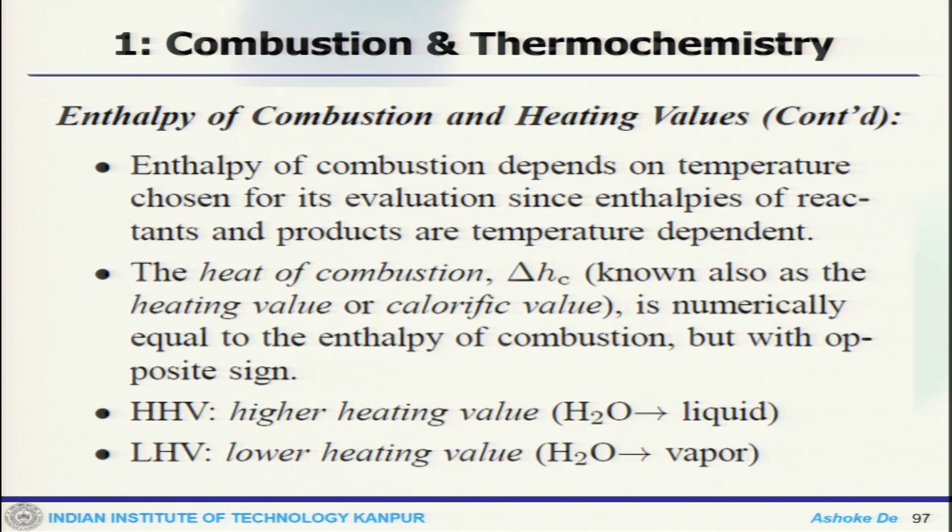Now, enthalpy of combustion also depends on the temperature chosen for its evaluation, since the enthalpies of reactants and products are temperature dependent. Obviously, the reactants are coming in, and when they react there is a heat release, so the product will have a different temperature. Now, the heat of combustion, delta Hc, also known as heating value or calorific value, is typically equal to the enthalpy of combustion, but with opposite sign.